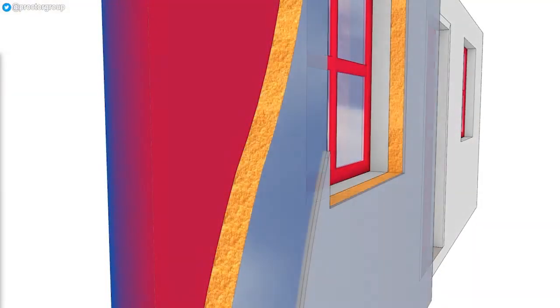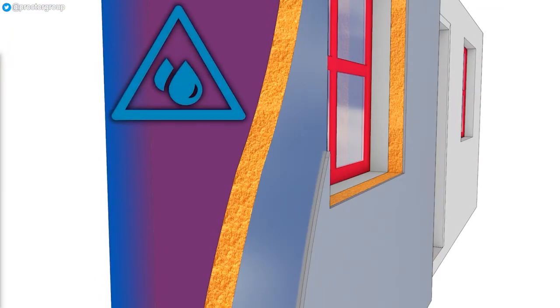Firstly, adding insulation of any type will reduce the temperature of the existing wall masonry, making it more likely that condensation will occur, and will occur further to the inside as there will be less heat penetrating from the living spaces to heat up the masonry.